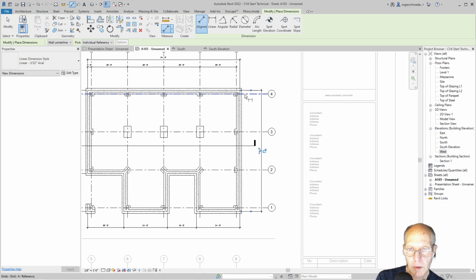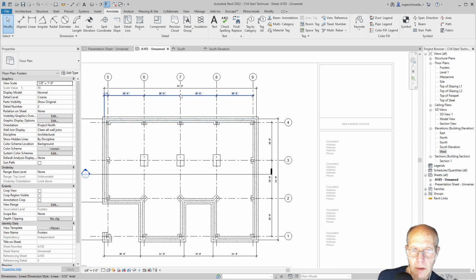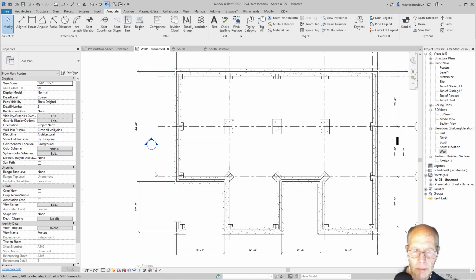And then once again, we don't know exactly what our grid lines are. So I'm going to select all 3 of these and pull those off. Oops. There we go. All right, so now we have those grid lines 20 foot in the vertical direction, 20 foot in the horizontal. The outside of foundation is 60 foot of our module plus 2 on either side gives us 64. We've got 80 along here plus 2 on each side gives us 84. And then over here we have 44, which is 20 plus two 2-foot offsets, which is 44. And then we're going from a corner to a corner, which is exactly the same as the module, so we get 20. So this all looks pretty good.